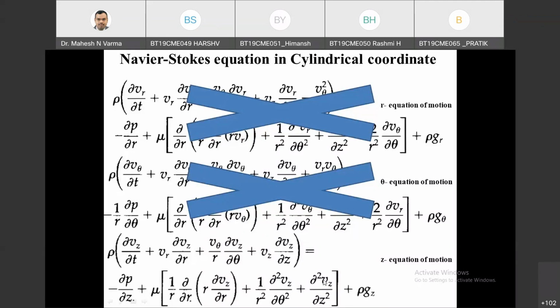No, this is not the reason actually. Wrong reason. Vz is not a function of z, and this is due to the continuity equation. Continuous flow, closed flow, non-accelerating flow. It is not because of what you told initially. It is not because of steady state.